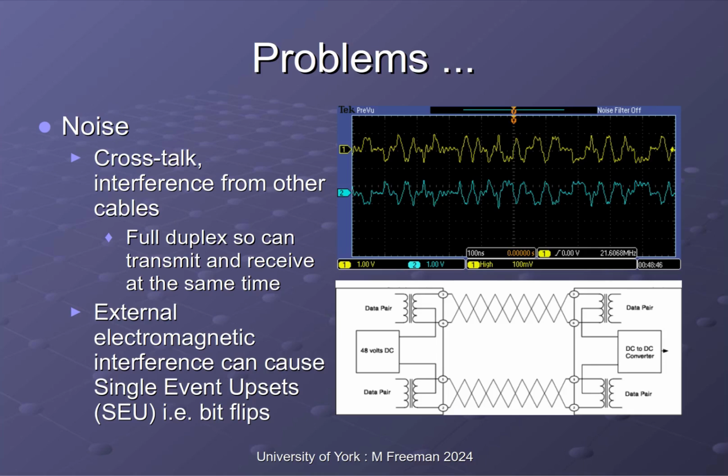So having differential signaling, sending the positive and the inverse down those twisted pairs, we can hopefully remove or at least reduce that part of the interference. So we can remove the noise generated internally in the cable due to inductive coupling between the wires, because we're cancelling out those magnetic fields. That doesn't help with capacitive coupling, so just the cables being physically adjacent to each other. So one way of reducing that one is to go with Cat6. Obviously you have that plastic spacer so you can move the cables away from each other. That would help. And also what we can do is take advantage of this differential signaling.